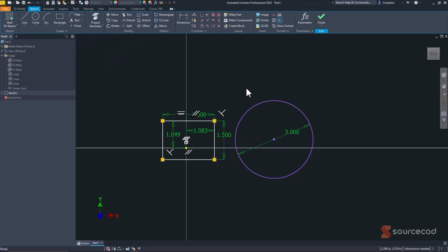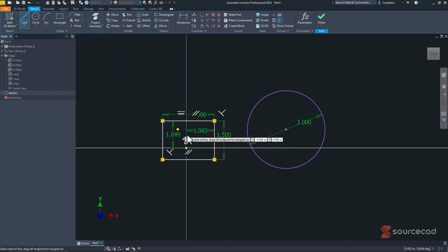So there might be times, and you might have heard some referred to as object lines or contour lines, but there are times when you need a help line, if you will. And what I mean by that is, I don't want Inventor to confuse these edges here and this one with what I'm about to draw up. So let's just potentially, I'm going to start here right at this center point. Just tie myself right into it. You can see it's got a big green dot. That means it's going to coincidentally constrain to that.